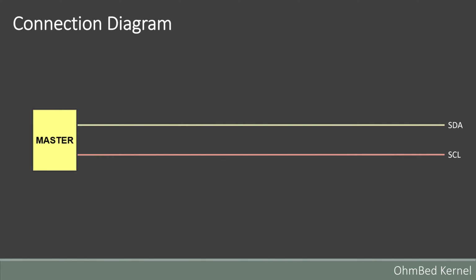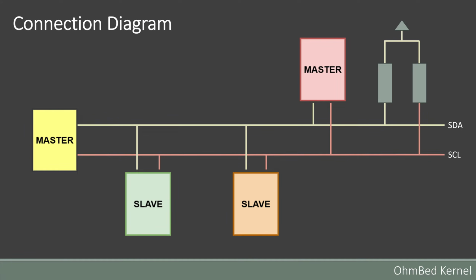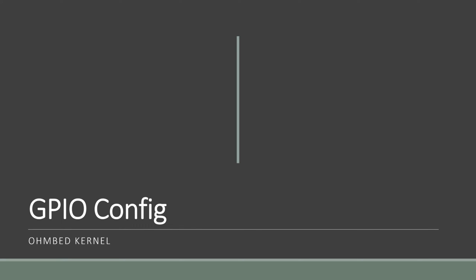It consists of a master and an I2C bus. On each bus wire, a pull-up resistor is required. We will learn more about these pull-up resistors later. On this bus, you can connect many devices such as sensors, I/O expanders, RTCs. Each device has its own address, so only 2 wires are needed. You can also connect multiple masters on the I2C bus.